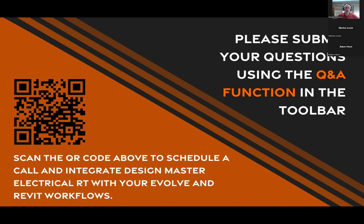Then the next question, which is something I forgot to do in my little demo. How is this one line created? I mean, this looks really cool and all, but how did I actually get to here? We can either create it, if you put your devices in Revit, we can then create the one line from it, or you can actually create the one line and have the devices in Revit created. So I have a whole section here that's not generated yet. So I can run our generate one line command, and I can select this panel, and it's going to create all of these panels downstream of it for us on the one line. So all those panels exist in the Revit model.